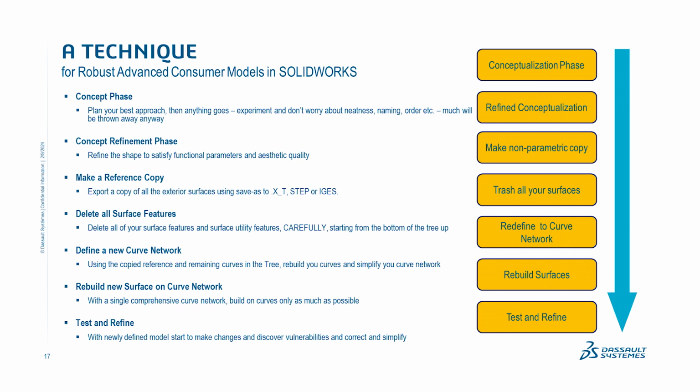So once you get that conceptual model for your shape and you feel good about it, you think it's a good approach, what I'm recommending is then I want you to trash all your surfaces. Yes, that's right. I want you to throw away all of your surfaces and keep your curves. Now, with that, you have a curve model, but you have a lot of dangling curves.